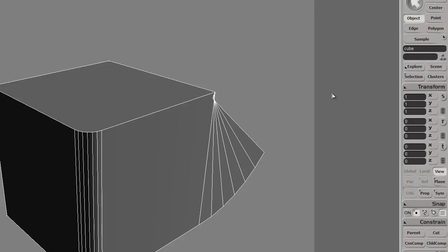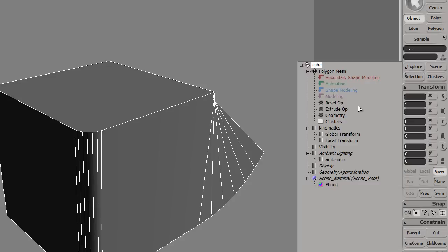Remember that? So basically the way it works is Softimage is making a record of everything you do to this object when it comes to polygon modeling, and it's placing it all under the modeling stack. Okay, see that? That's why it's under it. That's why this thing points down with an arrow and everything's under that. The way it works is the stuff that's at the top is the most recent operations I've done.